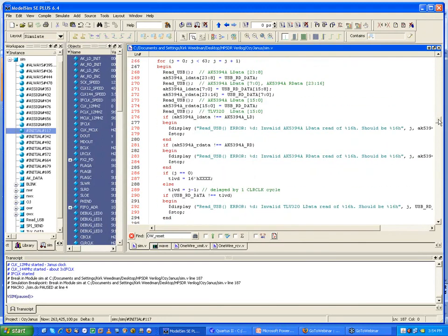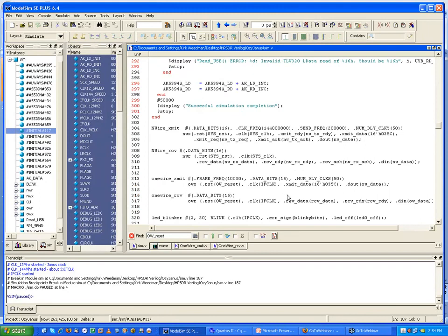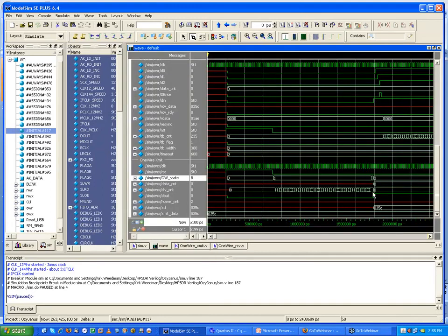Let's go back down. Okay, right here I said num delay clocks is 50, so I overrode it just so it wouldn't take forever, because normally this would be a very long time. So I overrode it just for test purposes for now, because all I'm doing is testing. Normally it's going to take like 200 milliseconds, and I don't want to wait 200 milliseconds of simulation time. So I said, okay, just 50 clocks instead of millions of clocks or whatever it takes. So I said 50, and sure enough, that's what we got here, a value of 50.